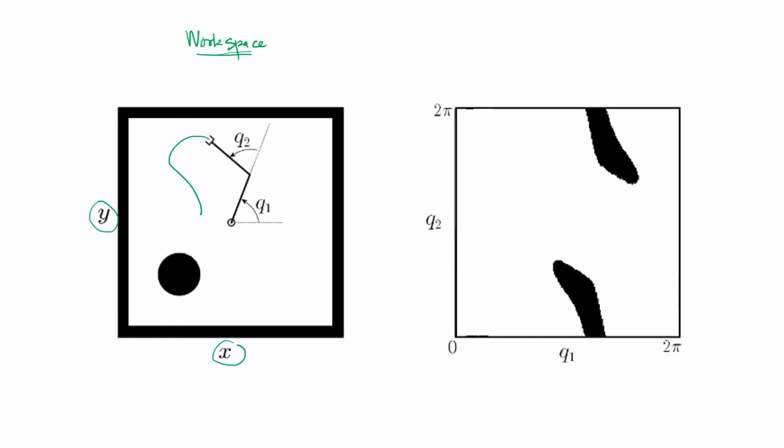It understands what is the configuration space, or the space corresponding to the joints. For example, there is one joint over here, there is another joint placed over there. So these two joints are going to become understandable, or these are the points which the robot can understand, and that is what we call configuration of the robot. So how this workspace should be transformed into a configuration space, that is going to be an important aspect to be considered as well.